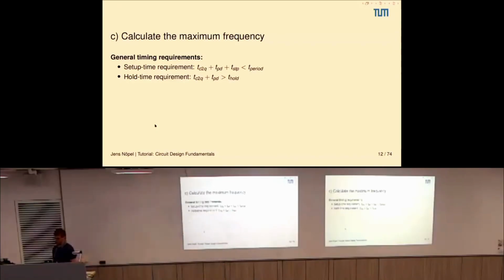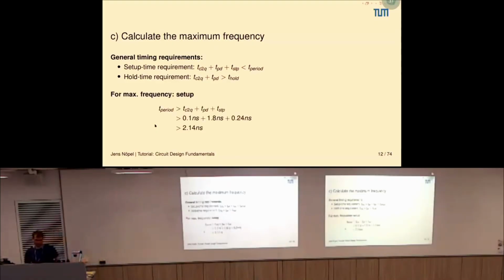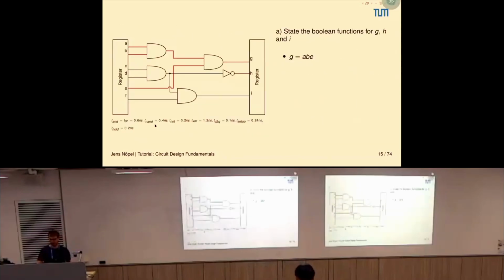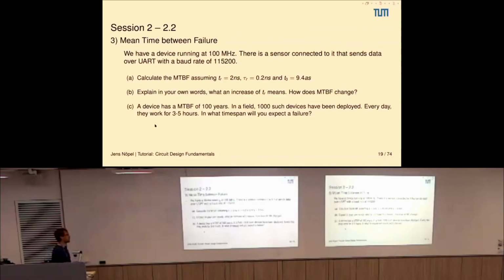circuit with. We also shortly discussed what hold time means and why both of those two requirements are necessary for digital circuits. And here you can see how you come from the period to the frequency for the first example. We did the exact same thing again and then ended up with calculating the mean time between failures.